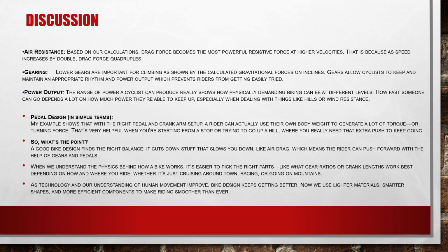Next, discussion. Based on calculations, drag force becomes the most powerful resistive force at higher velocities, because as speed doubles, drag force increases 4 times. For gearing, lower gears are important for climbing because they allow the cyclist to maintain appropriate rhythm and power output, which prevents the rider from getting easily tired.